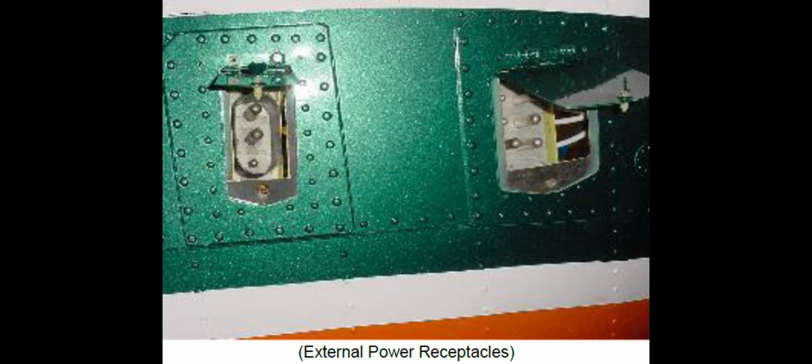Reset capability is provided through the external power reset switch, which energizes a relay in the external power monitor panel to supply power to the primary and monitored bus relays. If the fault remains, the relay within the panel will again de-energize.